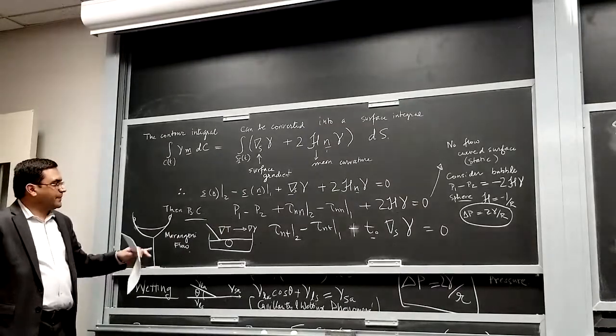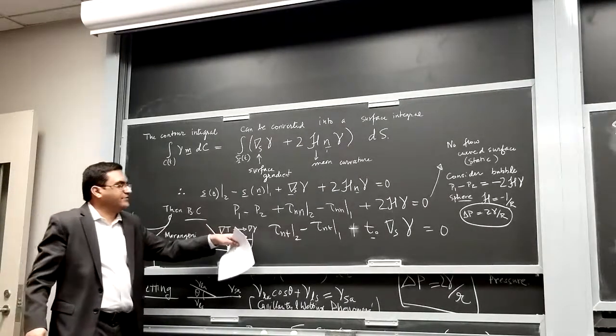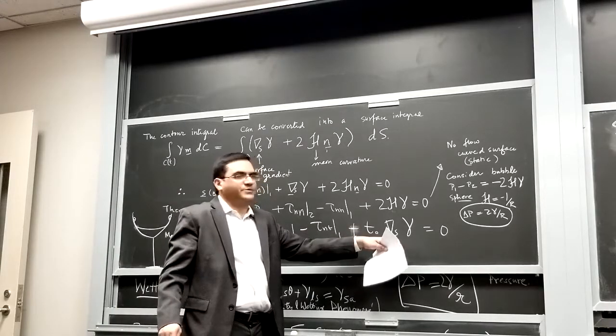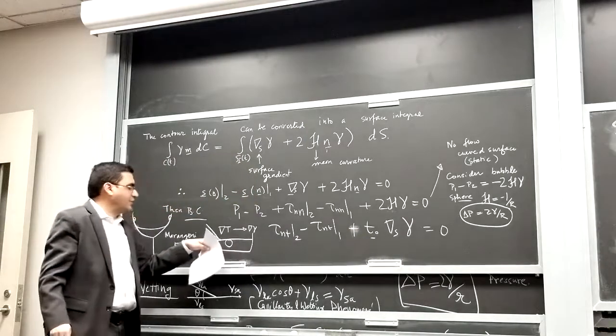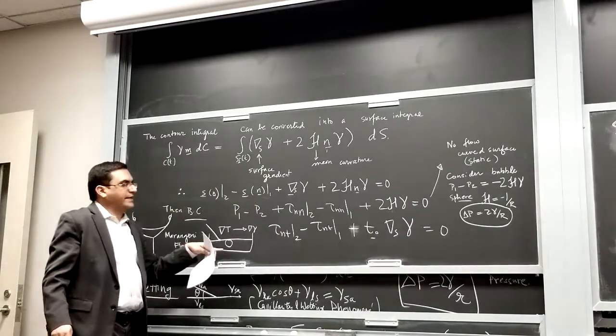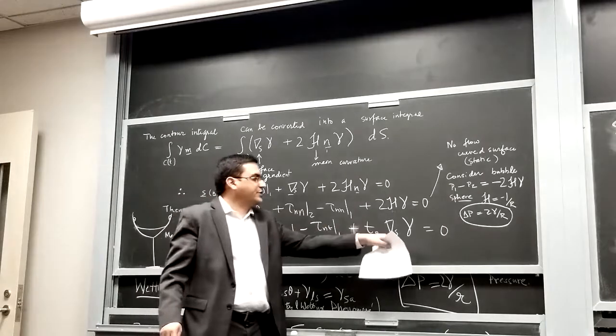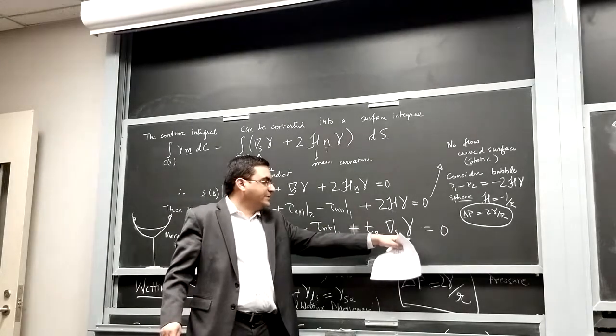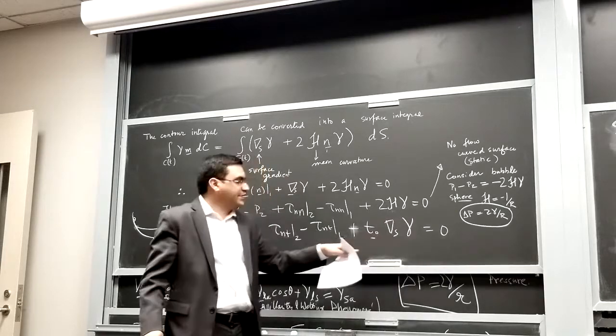These kinds of flows arise whenever you have non-uniform temperatures, sometimes because of evaporation, sometimes because you have contact with a heated surface. As soon as you get a concentration gradient or thermal gradient creating a gradient in surface tension, that's going to create a flow.